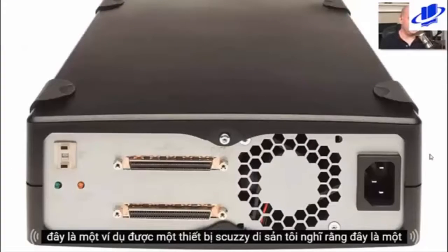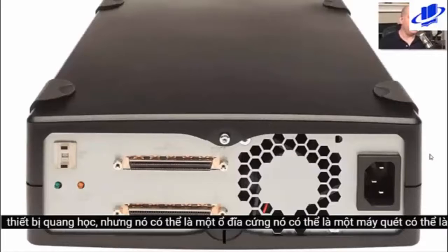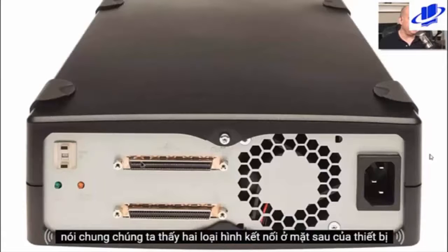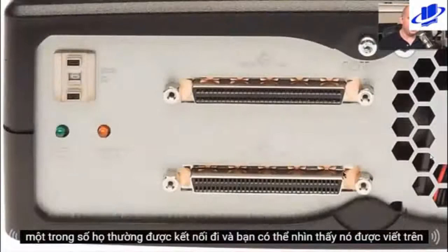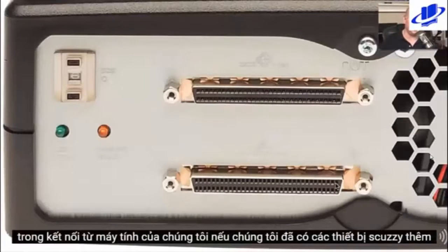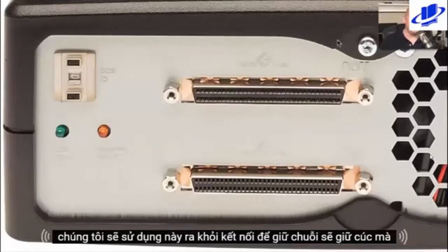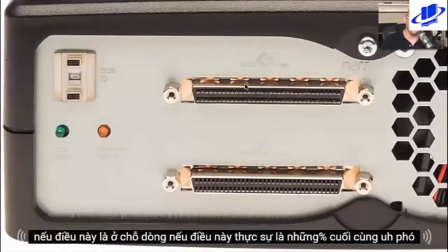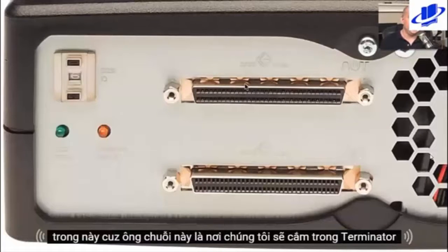Here's an example of a legacy SCSI device. I think this is an optical device, but it could be a hard drive, it could be a scanner, it could be anything else. Generally, we see two different types of connectors on the back of the device. One of them generally is the connection going in. You can see it written on the back of the device, where we would plug in the in connection from our computer. If we had additional SCSI devices, we would use this out connection to keep the string going, to keep that daisy chain going throughout the connection. If this was the end of the line, if this really was the last device in this SCSI chain, this is where we would plug in the terminator.